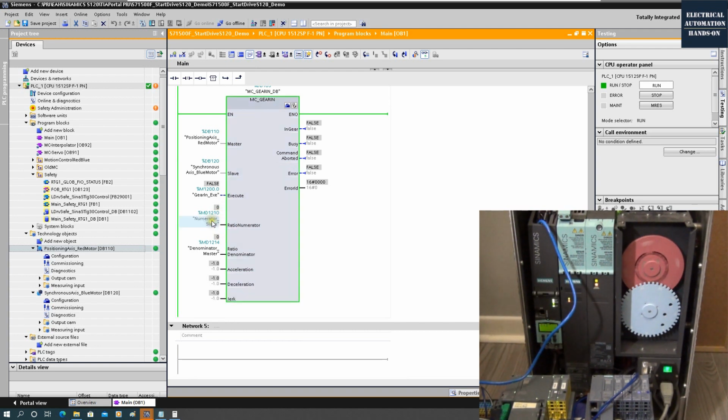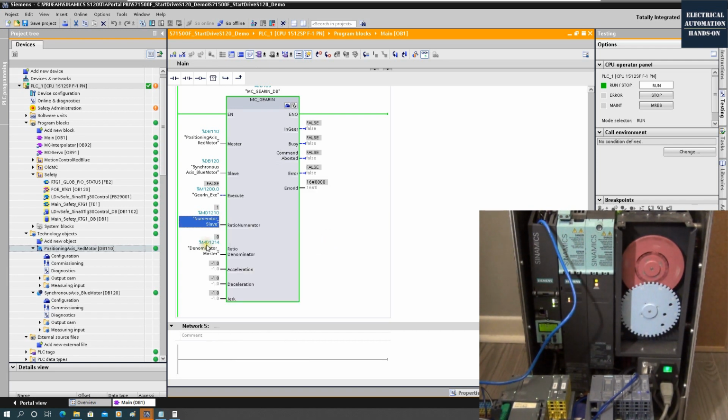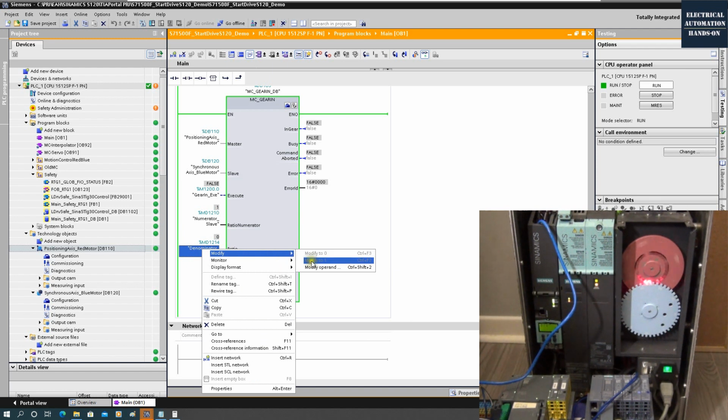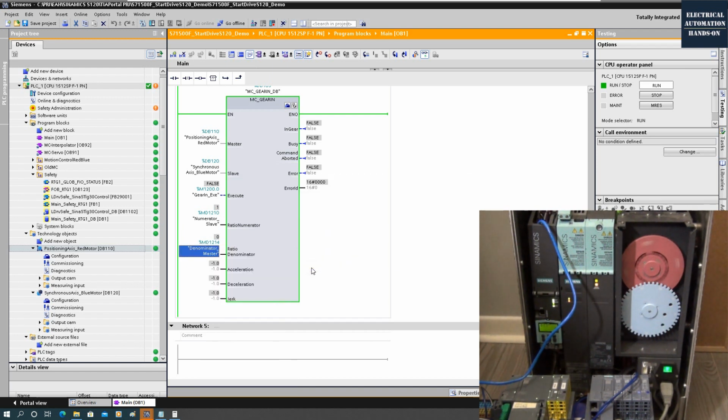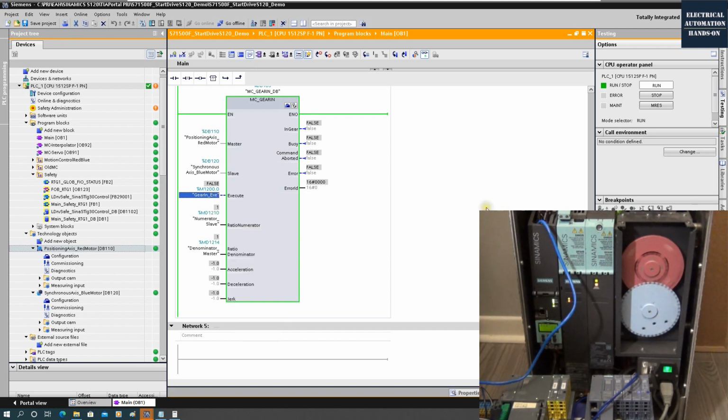For example, firstly I will set 1/1, so we can see the two motors' speeds could be the same. That means master and slave will run the same speed. Okay, and for acceleration and deceleration, here I will use the configuration from the synchronization, that dynamic value. Okay, now let's trigger this GearIn, and meantime let's watch this in gear. Fire. We will see the blue motor start up.